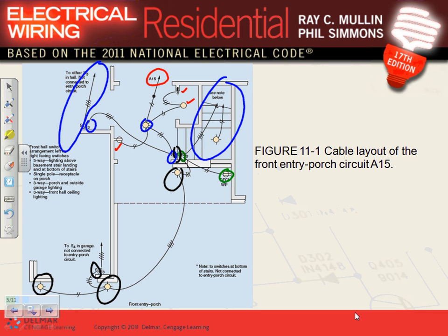Any question? We know what the hallway is. Every hallway 10 feet or more, you need a receptacle. Good idea, even if it's 8 feet, to have a receptacle. A porch needs a receptacle, GFCI weatherproof receptacle. It's a wet location, damp location, and a porch. The outside lights have to be rated for wet location because they're in a wet location.